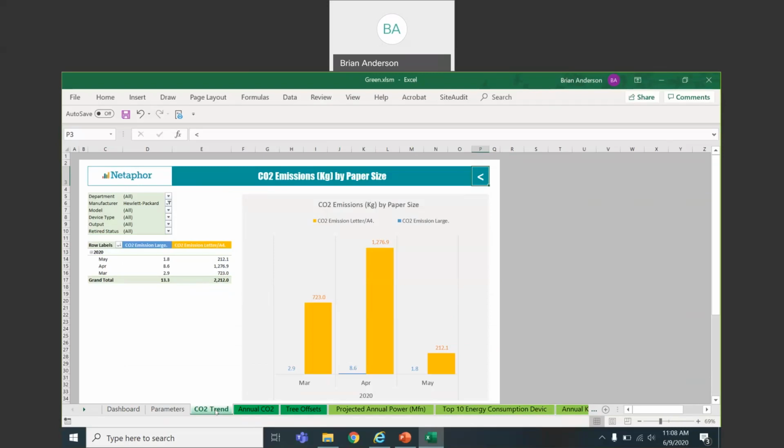And I want to note here that when you're using trends, they're based on the monitored period, which may or may not include a full month or quarter. So in this case, we say March, April, and May, and March may have some fewer days than all of March, and the same for May. April would be a full month. And so that would affect the carbon footprint. So it's advised if you're going to really use a trend that you should consider using periods longer than, say, 4 or 5 months, maybe 6 months and beyond.